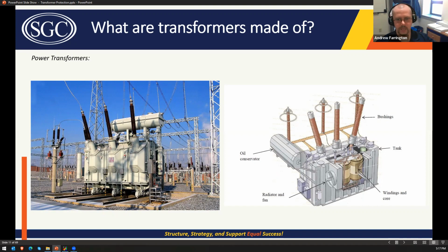So you may go right to the top of the transformer with plenty of room between the top of the oil and the transformer windings and core. And then you can inject nitrogen and lay a nitrogen blanket on top of the oil, between the top of the oil and the top of the transformer tank. And this keeps a positive pressure to keep the air out.